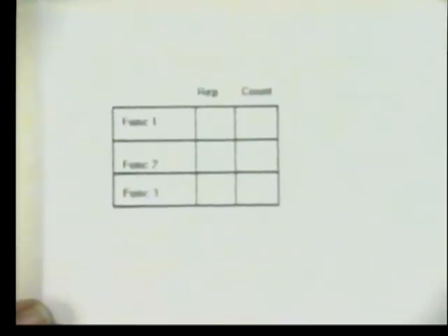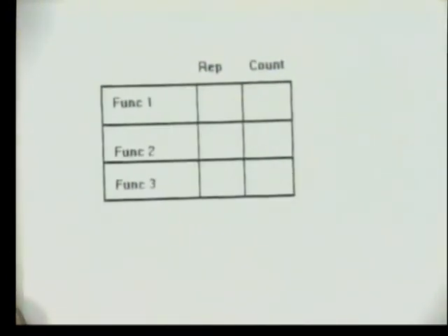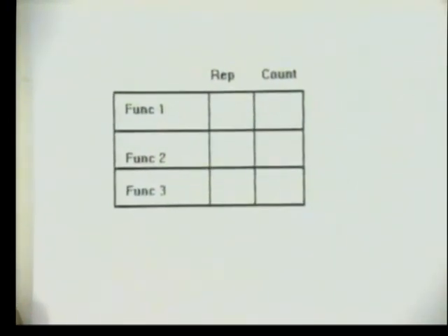But it still had the constraint that all of the functions had to be completed within a specific time frame. So that meant that we could develop a scheduled real-time interrupt without using a multitasking operating system. And I'm going to explain that structure to you bit at a time. How can we first achieve it? Well, firstly, we need to have some memory location that tells us some information about the operating system, the functions themselves. So the first thing we're going to do is we'll create a little array.